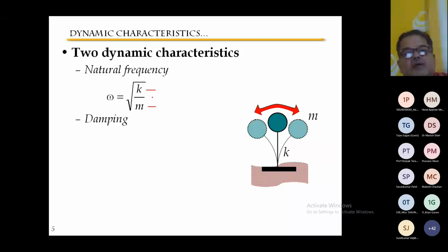So here, suppose a low frequency earthquake comes. If a low frequency earthquake comes, we know that the high-rise building has low frequency. If the high-rise has low frequency, then this earthquake will affect the high-rise building rather than a low-rise building. Suppose I assume it is a high frequency earthquake, or the earthquake contains high frequency, right? If the earthquake contains high frequency, then the low-rise building will be affected, right?